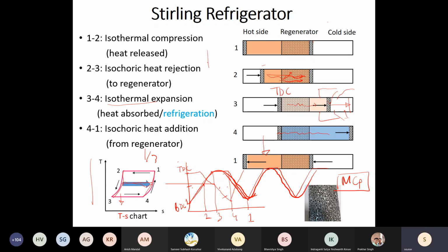So what we always discuss in heat transfer classes is one type of heat exchanger where you have two continuous streams of fluid which are transferring heat. There is another way of transferring heat. Let's say you have a single passage only, and hot gas passes through this passage, and after some time cold gas passes through this passage. You can use this passage itself to store the heat from the hot gas and release the same heat into the cold stream.